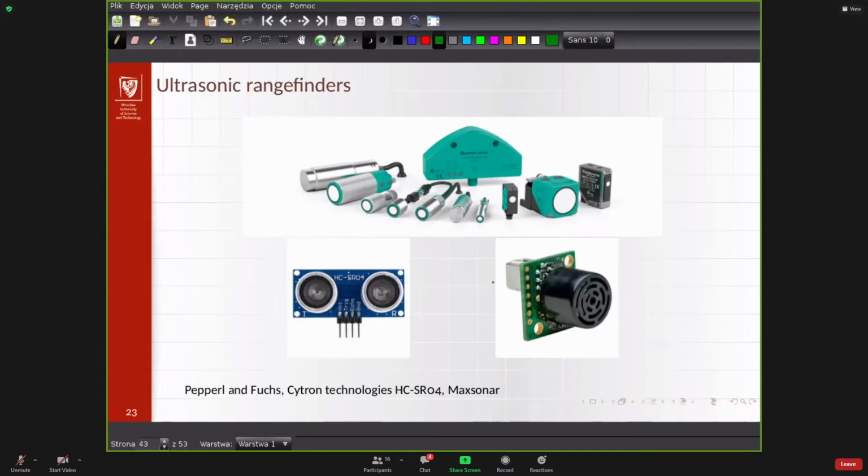Of course, it is a simpler construction with a dual mode, but the main problem with this solution is that you get a certain dead zone in front of the sensor, because if the object is too close, the wave that you were sending will already reflect and return before the module switches to the other mode.